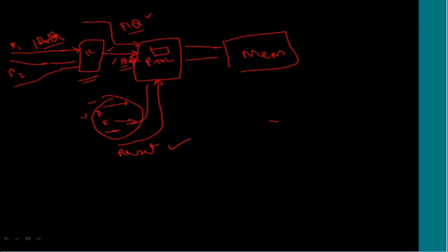So first is reset, just to recap on that. And then we have data abort. This is during data access to memory. If the exception is coming, then that will be given a higher priority, and then the rest will be FIQ. FIQ interrupt will be handled, and then IRQ. So this is the relative priority that the processor gives to interrupts.